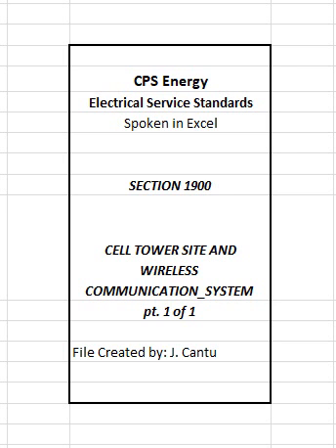Note 1. Customer shall be responsible for furnishing and installing meter pole in accordance with Section 1400 but may elect to have CPS Energy install at customer's expense. Note 2. Where meter pole structures require a concrete base, the conduit riser to the meter socket shall be installed within the concrete base and line up directly under the meter socket, refer to Figure 1902.